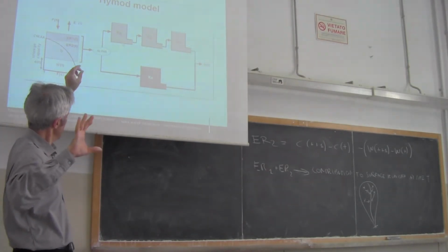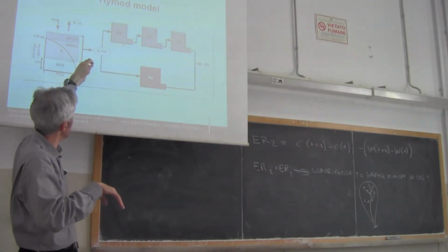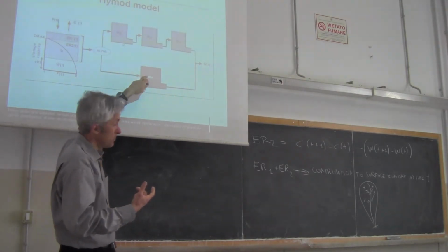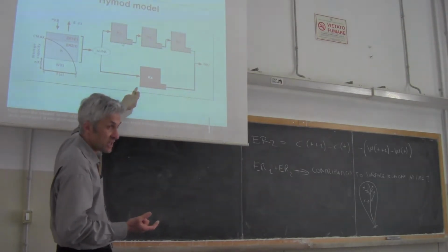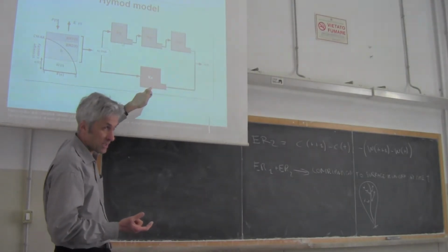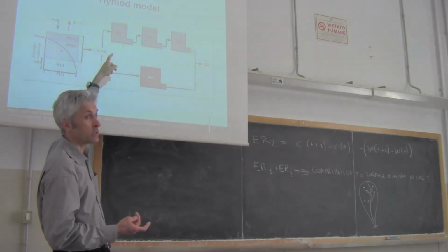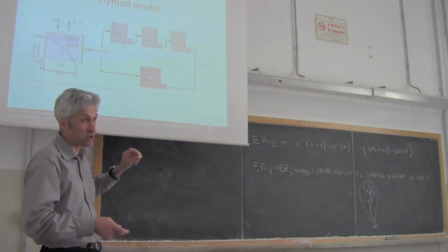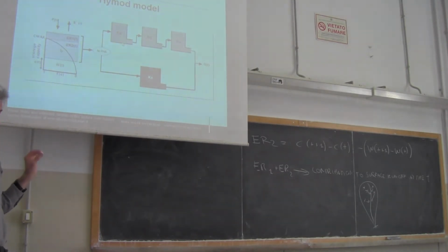So basically, in applying this conceptual scheme, I am introducing one more parameter to the model, which is alpha, one more, which is the constant k, called here ks, of the single linear reservoir, and one more, that is the constant k, called here kq, of the 3 linear reservoirs. They are assumed to have the same identical time parameter kq.